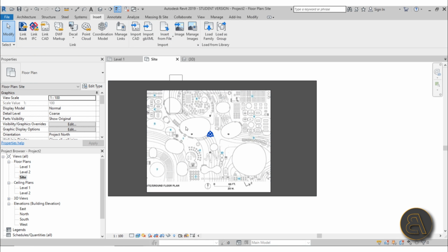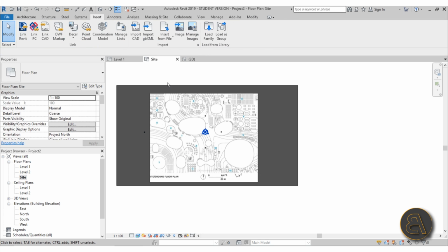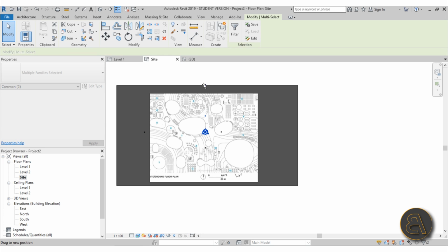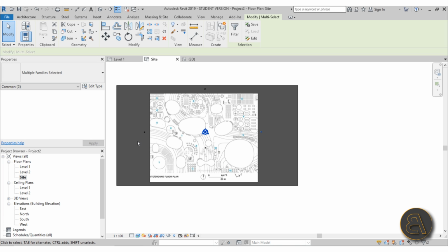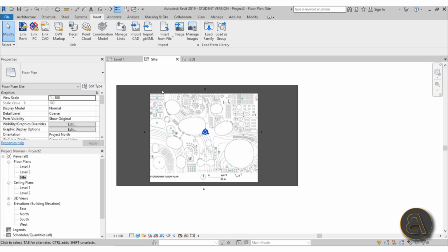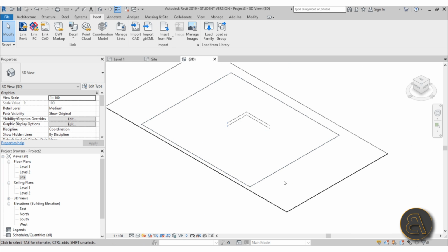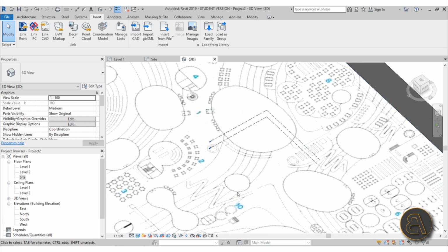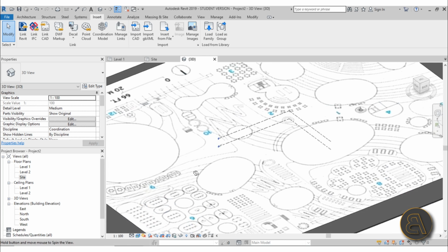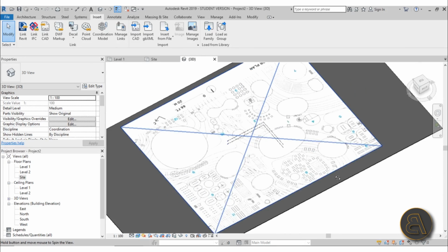And now I'm just going to select these elevation markers and move them out of the way of the image. This one as well, this one too, and the final last one here. Okay, and the point of this whole floor plan is if I now go into 3D, and look like this and turn this to realistic, now I can finally see my image and I can see those contour lines and I can start modeling this in 3D. That's what I wanted to do.